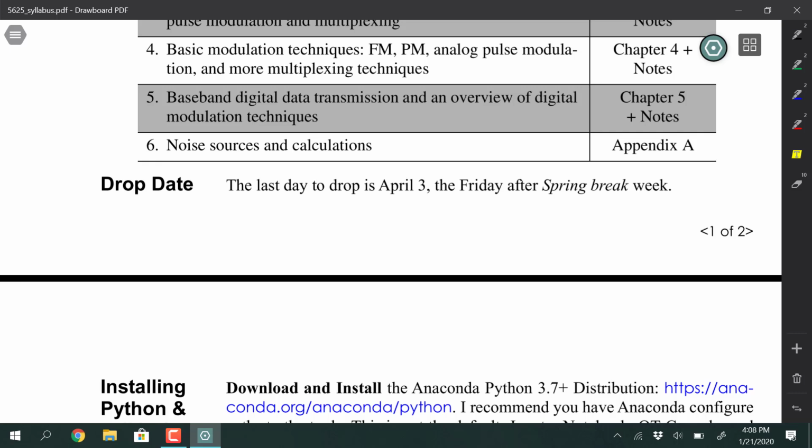But the thing that I always have to remind myself with our simulation tools today is that you can simulate pretty much everything on the computer, and whether you actually put the hardware in the link doesn't necessarily matter that much. It puts in some added realism, and some things that make your life hard, and that is the need for synchronization. That's why I have the class I'm teaching this semester on synchronization, because digital comms requires synchronization. Analog does not. Our ear hears it, and we recognize it, and it works. But if you have a bit stream and asynchronous clocks between the transmitter and the receiver, how do you get those locked up and synced with one another?